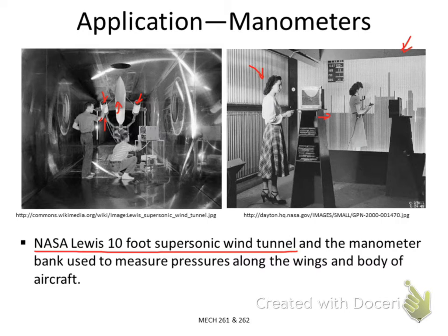Of course, nowadays we really don't have to use this device because it's purely mechanical. We always want to measure the pressure signal in voltage or current format, which is electronic. But still, the manometer is a popular pressure sensor device. When we introduce pressure sensors, in many textbooks it is always the first one in the pressure sensor part.